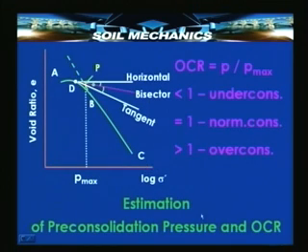There is a graphical procedure, and this is a very simple graphical procedure. You take the void ratio versus pressure curve plotted to log scale, draw a tangent at a point corresponding to the maximum curvature, then also draw the horizontal at that point, then the bisector of this angle, and where this bisector meets the straight line extension of this curve BC, that is this point P, that gives you the maximum pressure to which the given soil has been subjected to in the past.